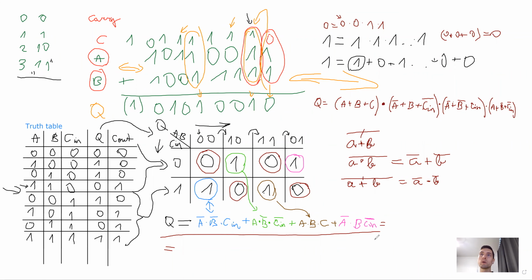Right now, the way that we wrote this equation, it performs two operations: multiplication, which is AND, and then additions, these pluses, which correspond to OR. But in the previous lesson, we studied that AND and OR are not optimal solutions because NAND and NOR are simpler, use fewer transistors, and perform faster. Because we could only get AND by using NAND and then NOT, and OR we obtained by taking NOR and then putting NOT at the end. So it was like extra work.